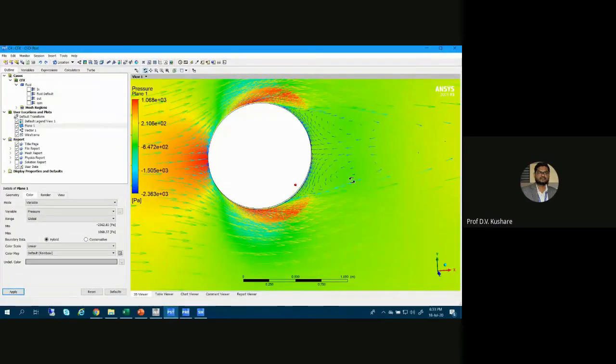Sir, I'm using different patterns for the surface roughness, like spherical or square or rectangular or different types of patterns. Can we simulate that? If it is very small, I think these are micro textured patterns. I think it will be difficult because you cannot mesh those kinds of things, and if you don't mesh it, your solution will not capture it. Okay, sir. Thank you.